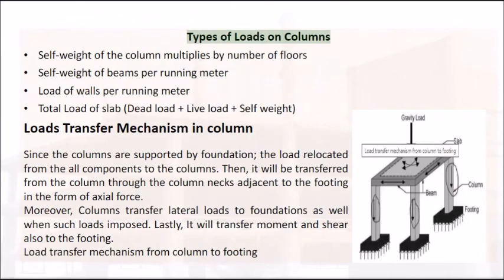Types of loads on columns. Self-weight of the column multiplied by the number of floors. Self-weight of beams per running meter. Load of walls per running meter. Total load of slab: dead load, live load, and self-weight.